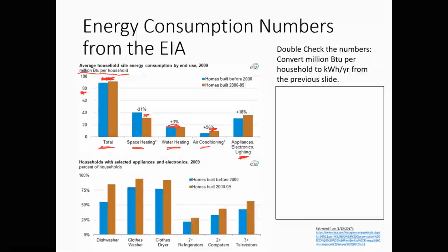They're more airtight. So if we don't have a means of dehumidifying, like in our air conditioning systems, when we're cooling, we're also dehumidifying, right? We saw that when we looked at the psychrometric chart. If we don't have a method for dehumidifying when our buildings are getting tight, we're going to run into moisture and mold problems in the summer. And again, it goes back to thinking of the building as a system.